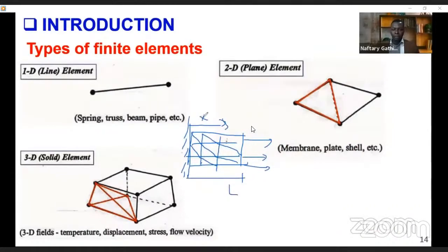So at any one point, you may want to get the strain or the stress distribution, in terms of contours. So what we are saying is that you need to calculate or obtain the stresses in this element, element 1, element 2, element 3, element 4, like that. And in each of the elements, the strain is constant. We call it the constant strain triangle, right? So that's just an overview. But let's see in application.